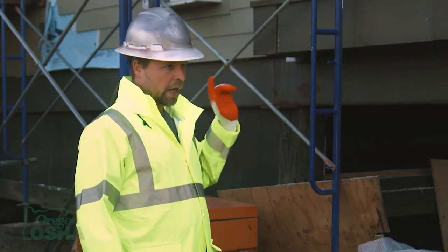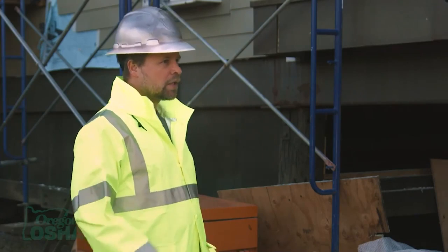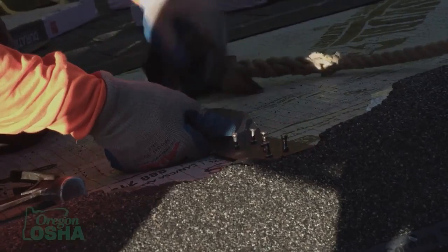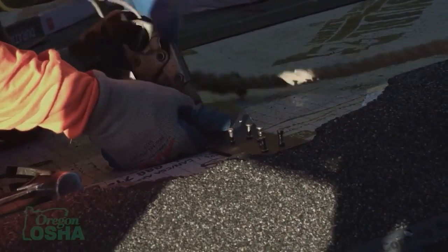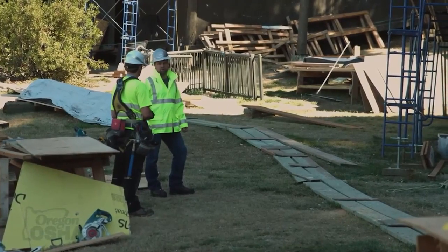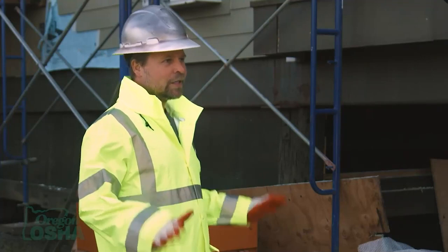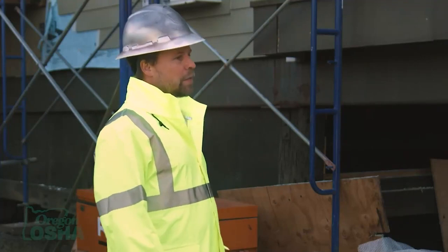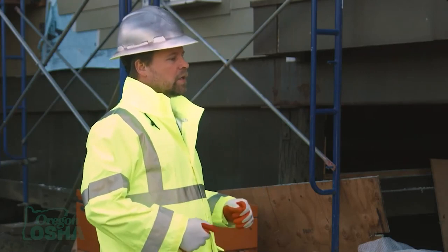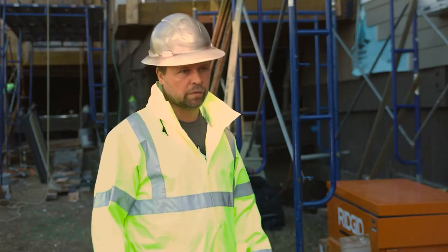If you have a rope hanging from the roof, you have to go make sure that it's installed properly. What if somebody just left it? Proper procedure: make sure it's hooked up properly, test it, and talk to your supervisor. The supervisor has to verify it so everybody knows, okay, green light, you can go ahead and use it. If it's not set up right, everything is worthless. It starts from the top: make sure the anchor is properly attached and the rope is properly attached. It could have been an old building, or it could have been rusted out, so maybe it was time to replace it.